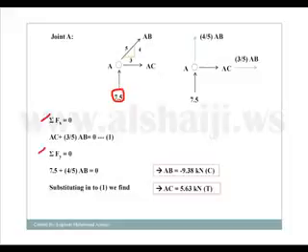Now, in order to apply the equations of equilibrium, that's sigma Fx and sigma Fy, all of my forces should be either along the x or the y. So all I do is resolve the AB force to its components.